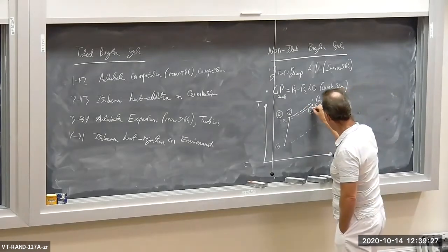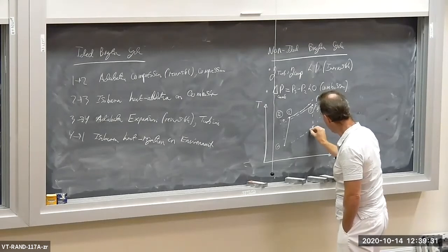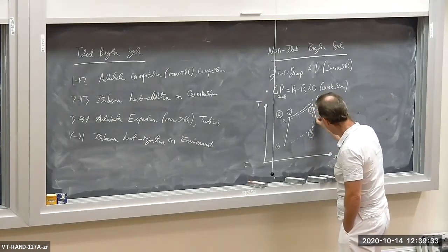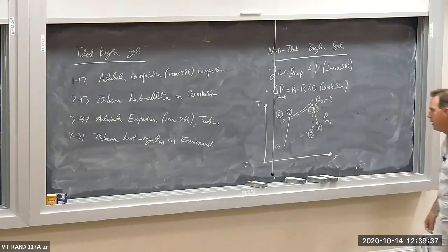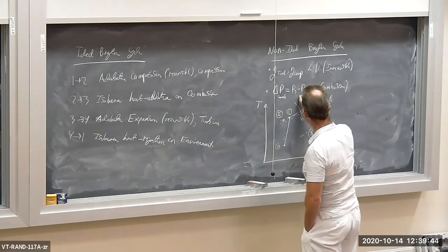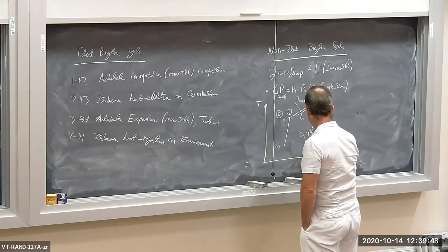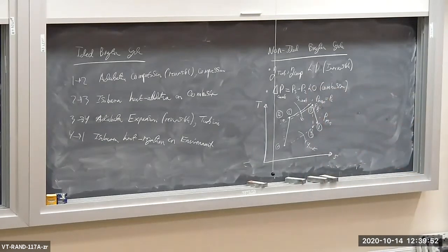And then we have the isentropic expansion process. So this is to 4 sub S. But the real turbine has some inefficiencies. So state 4 is actually a little bit to the right. So we have the heat addition process going on here in the combustor, Q combustor, and then we have the heat rejection process going on there.